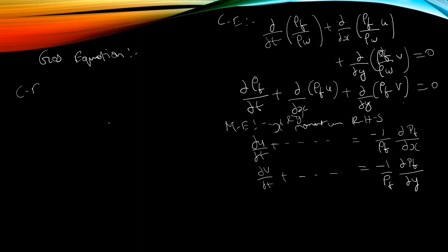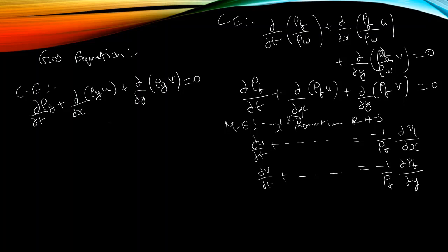So what is the continuity equation for gas? The same thing: ∂ρg/∂t plus ∂(ρg u)/∂x plus ∂(ρg v)/∂y equal to 0. Similarly, we are writing it for the momentum equation.